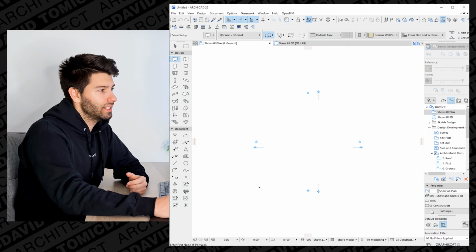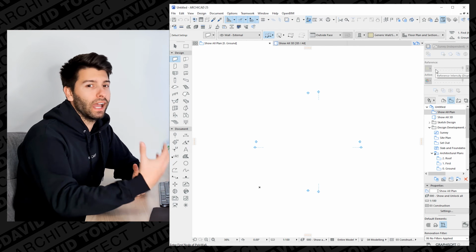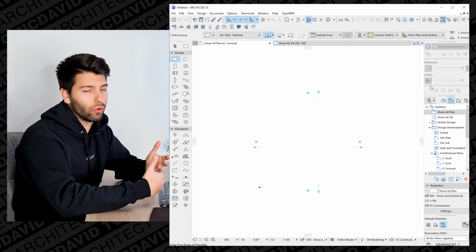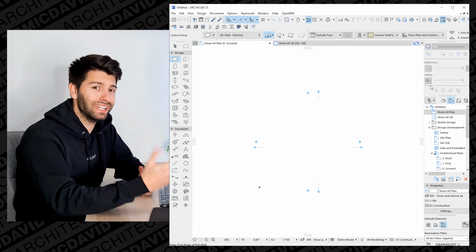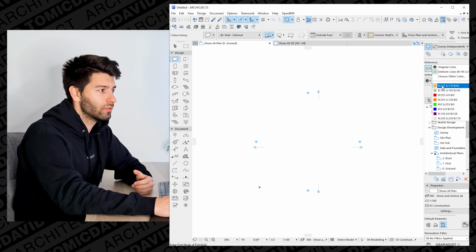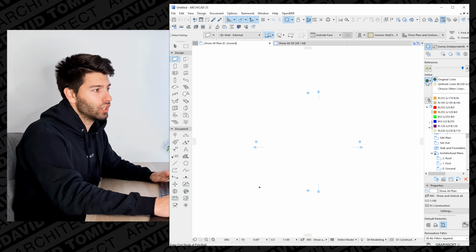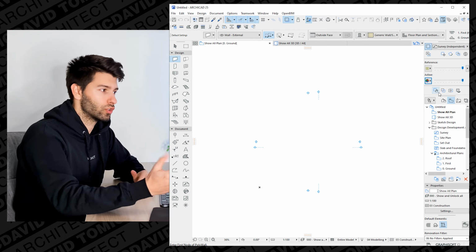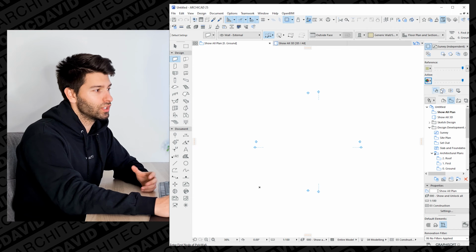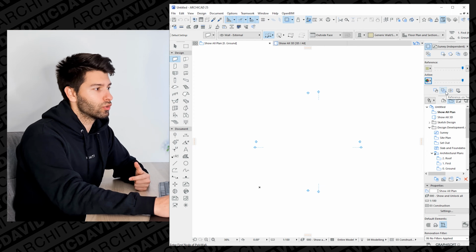What you're going to see on this right-hand panel is our trace and reference layer. If you're looking at the ground floor and want to see what's on the footings, you can activate the trace and reference layer to see what we've drawn on the floor below, floor above, or any selected floor. You can activate it, change the color of the trace reference. You can change the opacity as well, and you can also change the active color so it can contrast better. If you're struggling to see through the transparency layers, you have these different options of hiding and showing different layers. They each do individual things depending on what you're trying to achieve.